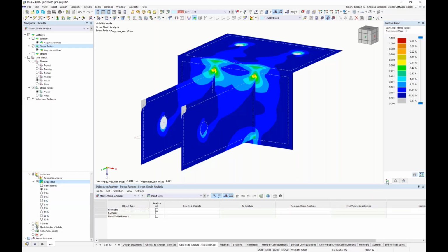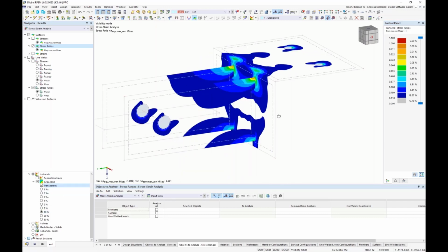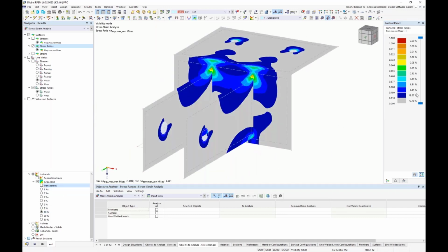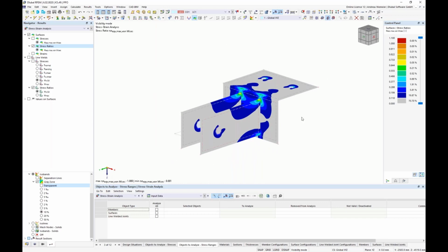You can say here, please hide the 1 promille of uninteresting part, or maybe 5 promille, or maybe 10%. Then you see, okay, it hid now 10% of the uninteresting stress, what is not so close to the limit, and the rest will be visualized, and then you can make a nice picture without playing with the colored panel, and see directly where it's interesting. And you see, okay, interesting is here the load introduction, here the load introduction, here the load overtake from this to this element.